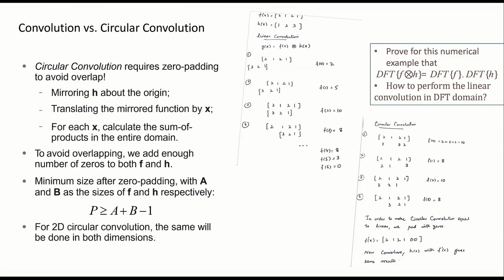Now the circular convolution, since the discrete Fourier transform is periodic, it has to repeat itself, right? So it means that you again have the same thing, and before also you have this. So if I start, this will be multiplied with this, and similarly, if I go here at the end, it will be 3, 2, 1. Another way of doing it is that I assume that this is connected. So if this is 1, the 2, 3 is here. Sometimes that is easier, and sometimes it depends how you're thinking.